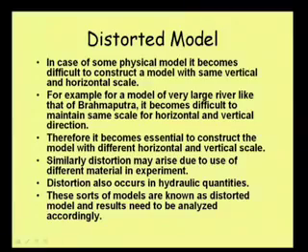If we put the same scale 1:100, suppose the depth is 10 meter, then if we apply a scale of 1:100 in the model, we will be left with a depth of what? Say 1 centimeter, if the depth is 10 meter. Well, not 1 centimeter, so 10 centimeter depth we will be getting. Now that creates a problem. So we get this distorted model. In many cases it becomes necessary to have a distorted model.